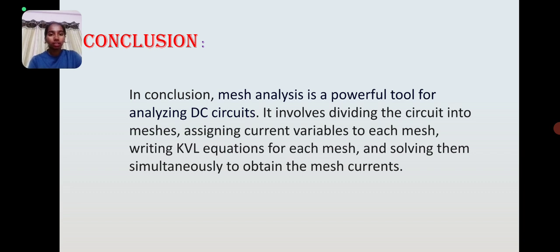Looking into the conclusion, mesh analysis is a powerful tool for analyzing DC circuits. It involves dividing the circuit into meshes and assigning current variables to each mesh, writing KVL equations for each mesh, and solving them simultaneously to obtain the mesh currents.